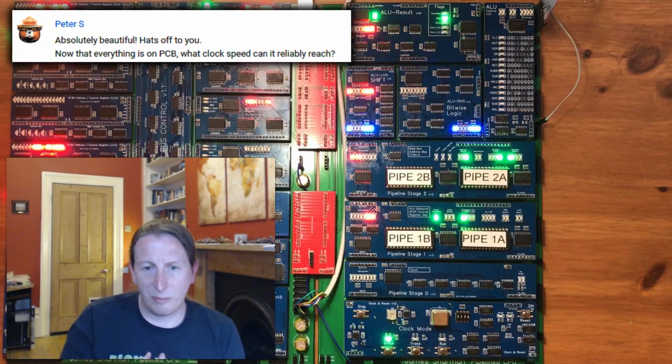The UART is limited by the baud rate set on the device. The LCD, many of the operations triggered the busy flag, which is why we extended that circuit. So at the moment, if I go from 1 megahertz to 2.5 megahertz, the wait loops in the code just end up waiting for longer.